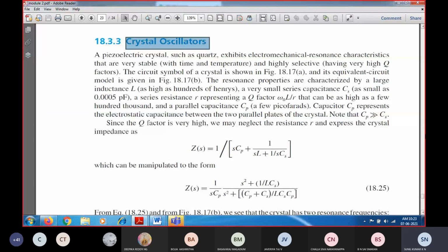So with it, the clock will be generated by using these oscillators. A 33 megahertz clock, you will be seeing in microcontrollers, where they explain the crystal oscillator frequency of the microcontroller is 33.33 megahertz, like that they may have told, right? At the same time, an 11.0592 megahertz clock frequency will be required for this Atmel 8051 microcontroller, like that they might have told.